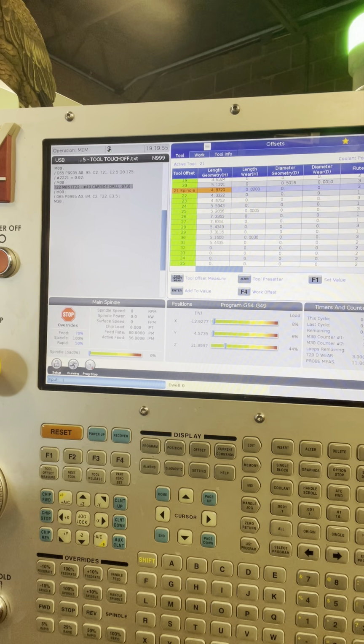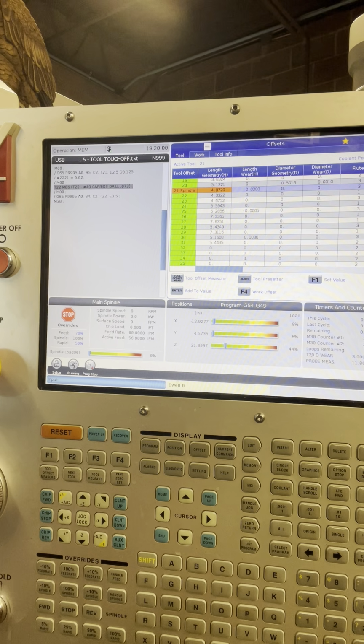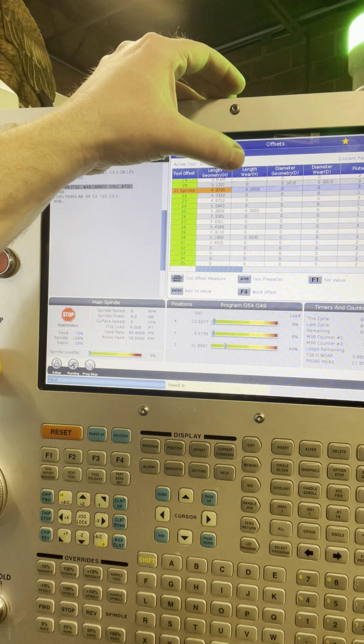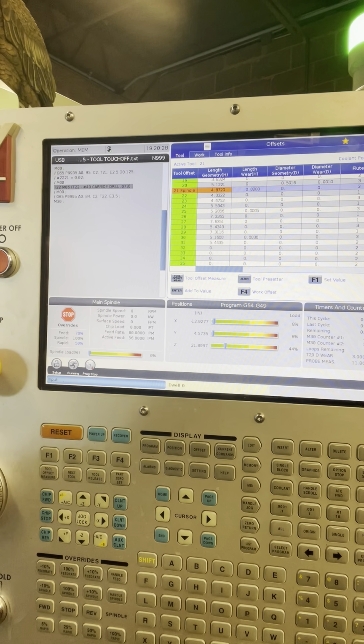So this is our example of a spot drill or any kind of tool where you want to make sure that you drop down to where you want it to be, because you never know what that distance is. Ours are fairly consistent, so I know where to expect them. We're around 10,000, so it's 8, 12, 10, somewhere around there. If I'm going negative in here, I know there's something wrong, or maybe it's programmed differently than I thought. But it's a good way to see what's going on. If you see it's still 20, you know that you didn't adjust your tool or anything. If you ever do any